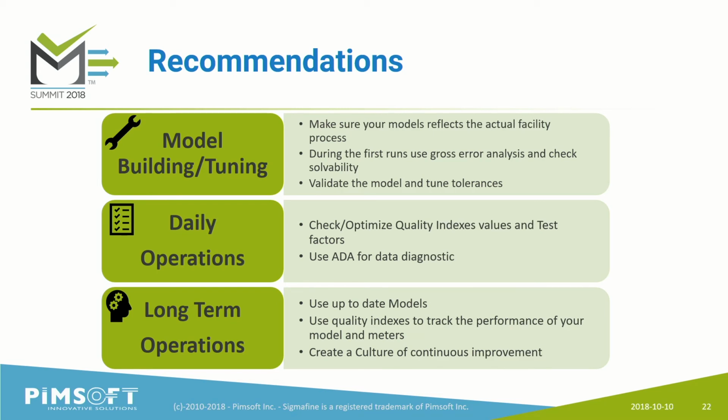In the daily operation, we recommend, again, to use the statistical factors to track the behavior of your meters and of your balance. So use the DX indicator, and use the T3 indicator also to track the performance of your meters. In the long term, for sure, you always have to remember to keep your model up to date.